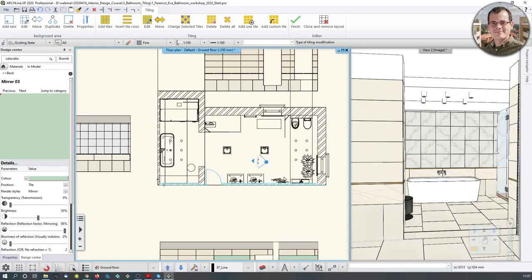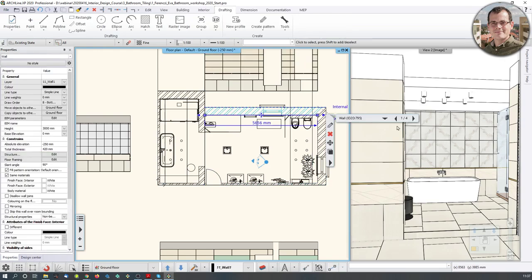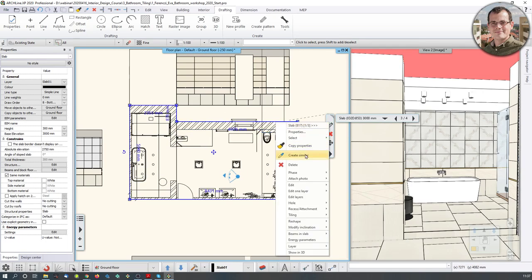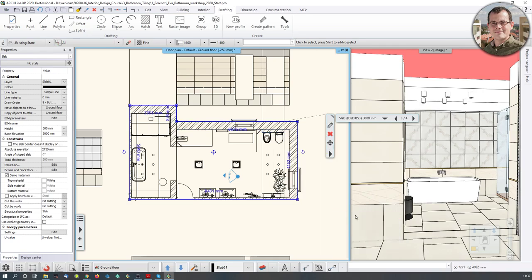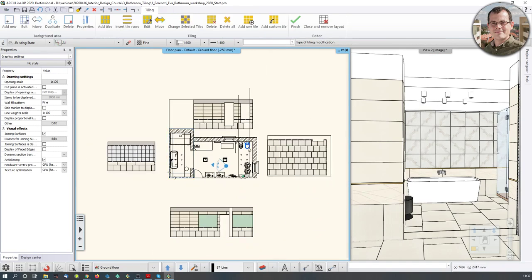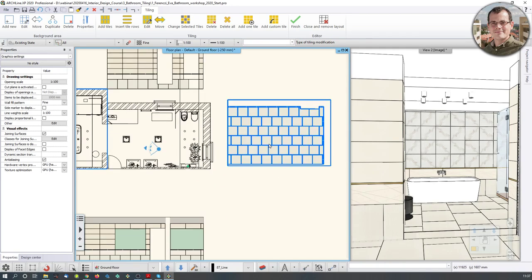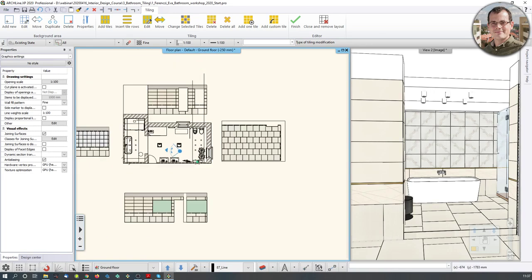If you want to create another one, or you get another one with the slab, you just click on the slab. Now I can't click on the slab right now because I have a wall above it, but you already know that with this jump list you can quickly find the slab. There are actually 2 slab pieces, I think I need this one. So if I right click and I go with tiling and the tiling on floor tool, then these things are automatically created. You can push this back to the original drawing, but that's the way to sort of get a visual representation of how your tiles look like. So now again, I could be going in and creating multiple multi-layered styles over here, but that's the general idea.